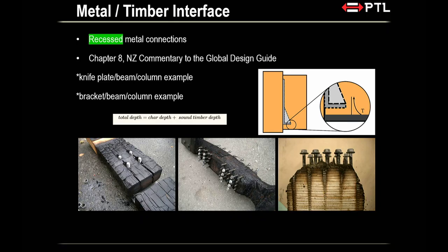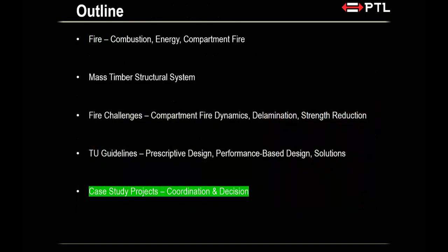But really, what I wanted to summarize here, the whole idea, is the total depth that you need to allow. This particular picture shows the char depth that you calculated, and also what they call the sound timber depth that you have to include in there. So there's some example in there that will help you.